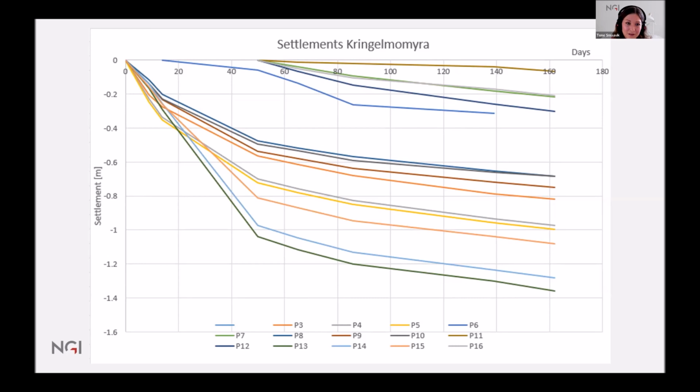Well, there shouldn't be too much settlement within the fill. Correct, because it's compact, right? But when you start measuring on top of the fill, a lot of the settlement has happened already as you build it up. That's why you see less settlement in the measurements starting from the top of the fill, because it does happen fairly quickly.